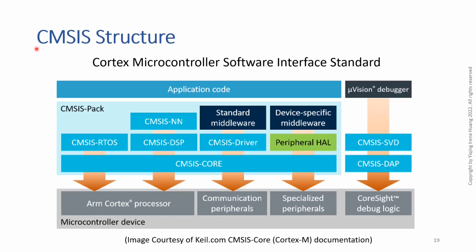So for the HelloWorld application, we only create the HelloWorld main file. The rest of the files actually come from the software stack called Cortex Microcontroller Software Interface Standard. So here's the microcontroller device, and this particular one, the CMSIS core, that layer of software provides us lots of functions that we don't need to write, and that makes our life to write the microcontroller application a lot easier.